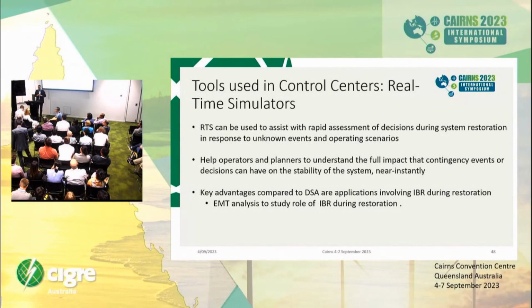Yeah, so I would say there is no silver bullet which can solve everything. It depends on how good your situational awareness network is, whether it's coming from PMUs, or drones which can go and tell you what your system state is and what lines are damaged. If you have lost SCADA, do you have functional observability in your system? Well-established cranking paths are fine because you practiced on them and you can energize them if they are viable.